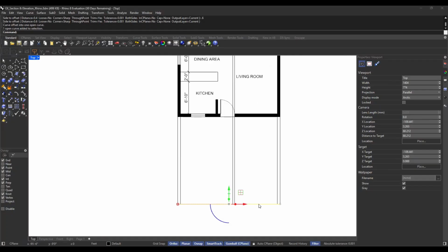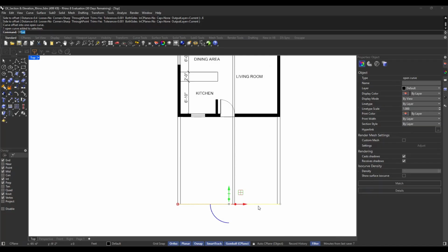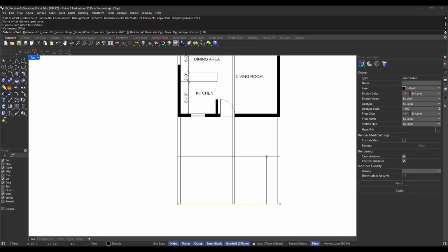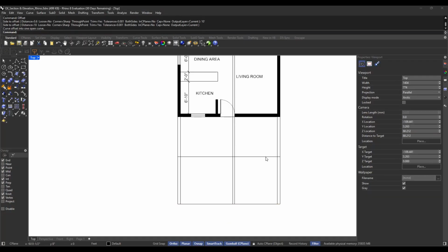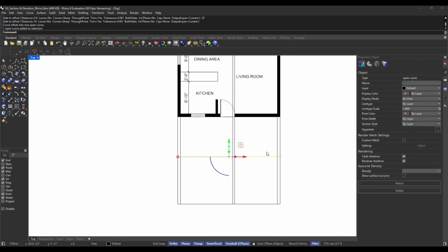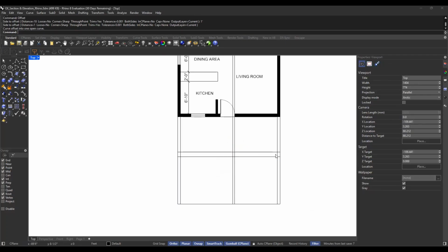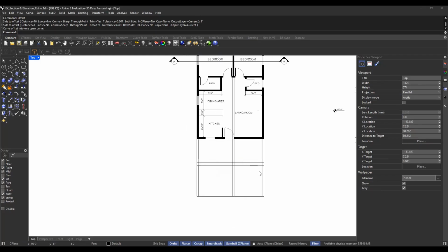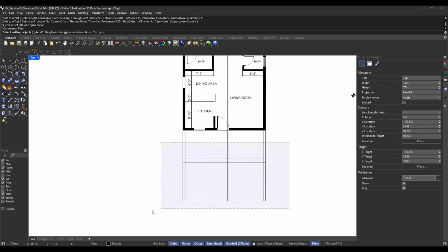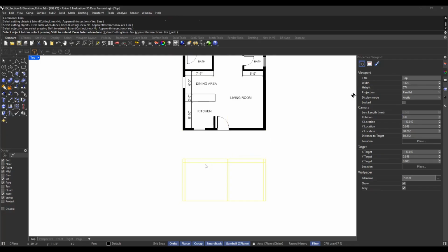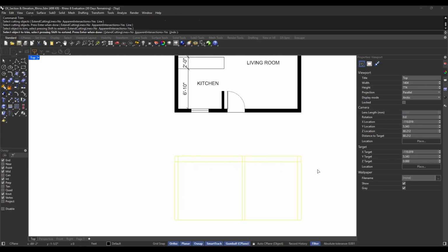As you remember, I'm gonna offset this line, and the height was 10 feet, and hit enter, and we have 1 foot ceilings. So I'm gonna just type 1 foot and hit enter. In section, we see the thickness, right? The wall and ceilings and the floor, right? So I'm gonna just clean it up because right now I have the sections, the height and everything.